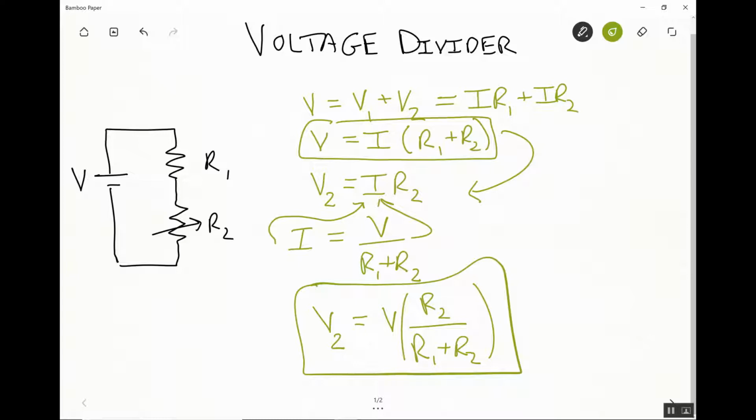All right, so what we have is that the amount of voltage that is utilized by resistor 2, and again, here in this case, it's a photoresistor, is a function of the total voltage being supplied to the circuit, which is a constant, 5 volts if it's an Arduino Uno digital input-output pin. It's a function of that and R1, but then also R2.